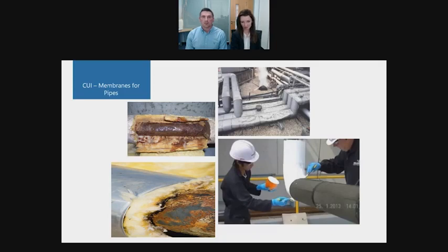If there is any water present, then ideal corrosion conditions may be created within the insulation layer, as rock wool or foam glass can absorb the moisture. The result could be general corrosion across the surface of the equipment, or even more seriously, localized pitting. Corrosion can occur with consequent premature failure of the equipment, so it is important to protect the insulated pipes.